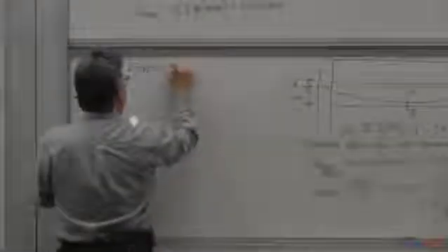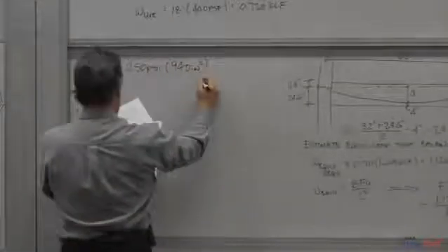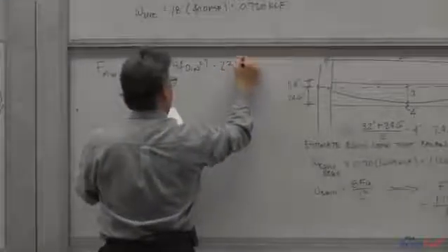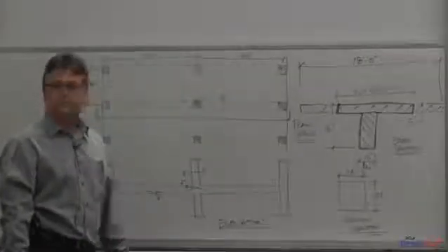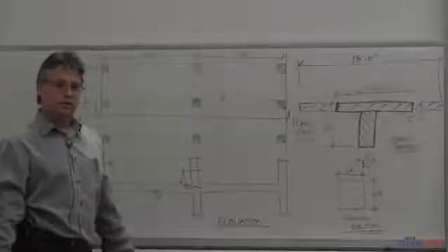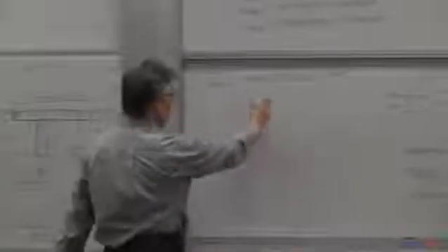Also said that the minimum force is going to be based on 250 psi on the cross section, which is 940 square inches. That would require 235 kips. For my estimate of the number of tendons that I'm going to use, what number should I use? 267. It's the bigger one. 267 will obviously give me more than the 250 psi. If I only use this force, I'm balancing much less than the 70% of the concrete weight. So